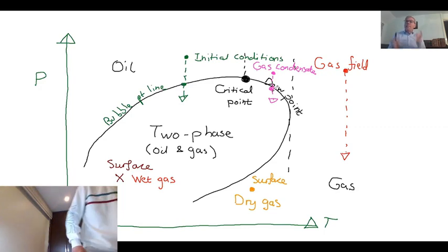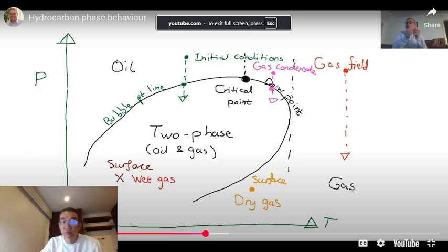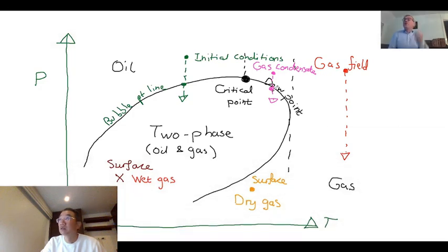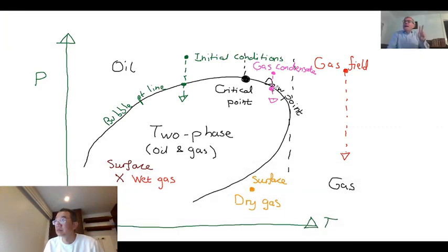So what happens is you start producing gas. It's a gas field. Normally that gas will flow quite readily, and so you have a large pressure drop. So at the well, the pressure is quite low. Then what happens is you drop below the dew point near the well where you're producing your gas. So what happens is the liquid drops out of solution and is in the pore space of the rock. So there are two bad things that represents. The first one is the most valuable part of your hydrocarbons is the liquid, right? Because it's a light oil. It's a very valuable oil.